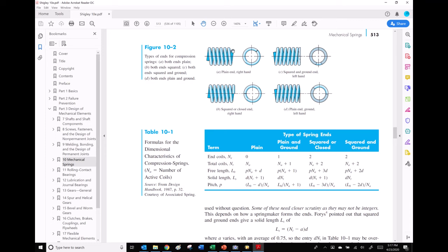One thing that you could do is you could bend that little last coil in so that it closes it, right? And that kind of in turn kind of squares the face off. So now at least has a little bit of an edge to sit on instead of just a single point. Or what you could do is you could close it like that, and then you could take a grinder and you could grind off some more. So now you have a lot more of a flat area. Or if you're just really lazy and didn't feel like doing that, you could just grind off the thing, and now it's going to come to like a real thin point right here. So let me show you what that looks like in a couple examples.